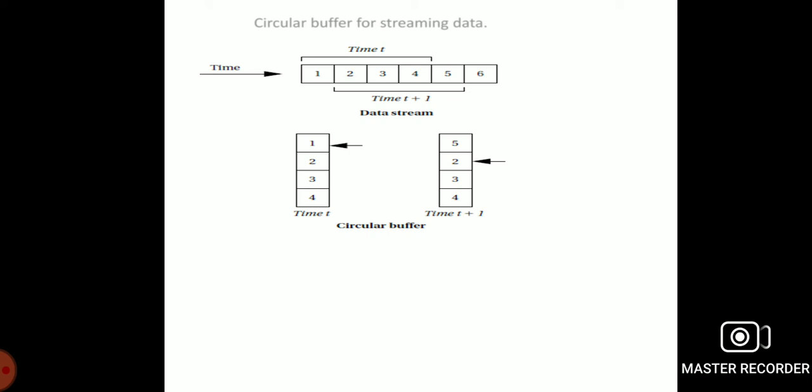The buffer pointer points to the location at which the next sample will be placed. Okay, we can understand. So every time we add a sample of data, it automatically overwrites the oldest sample, which is the one that needs to be thrown out. When the pointer gets to the end of the buffer, it wraps around to the top.